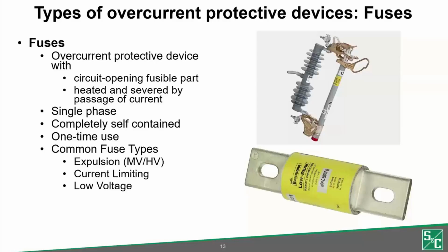The common types of medium voltage fuses are the current limiting fuse and the expulsion fuse. The current limiting fuse has a high interrupting capability. When seeing currents of high magnitude, the fusible element melts fast, with the arcs quickly extinguishing, and it limits the magnitude of short circuit currents through it. The other type, the expulsion fuse: the internal arcs that are produced when the fusible element starts to melt on seeing fault currents expel gases that result in opening of the circuit.